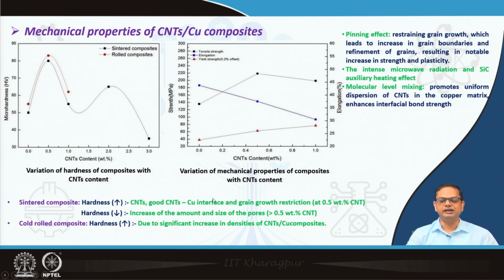is that as we have seen earlier, there is molecular level mixing of CNT and copper. So, there is homogeneous mixing. Along with that, Cu is growing on the surface of CNT, the way copper was synthesized from copper acetate to copper oxide to ultimately elemental copper. So, basically it is growing on the surface of these CNT particles. So, that is again good, because that leads to improvement in the interfacial bonding. It improves the wettability. All right.